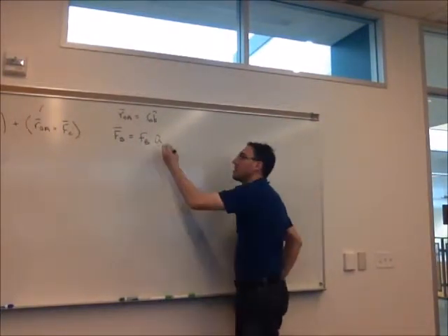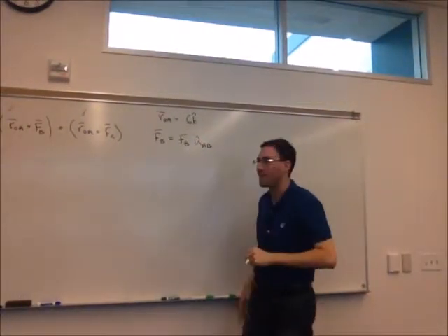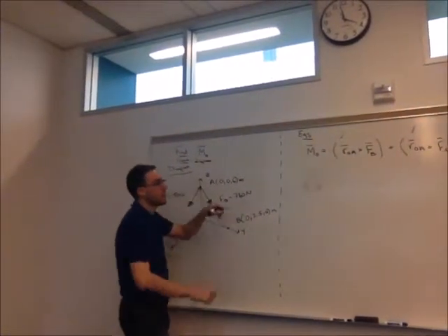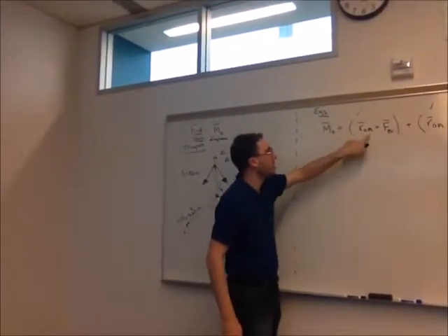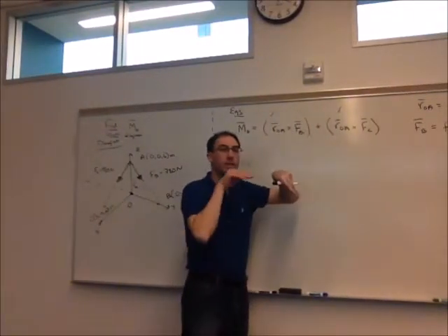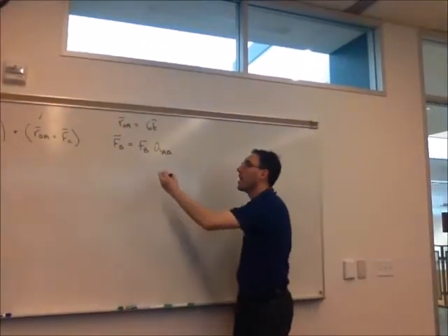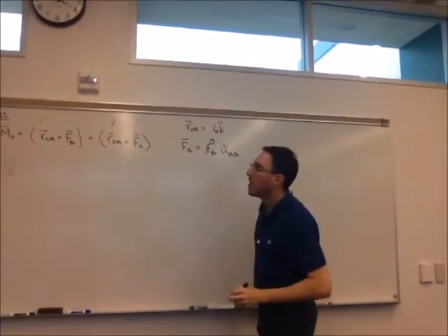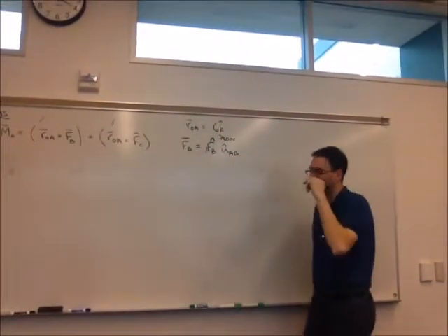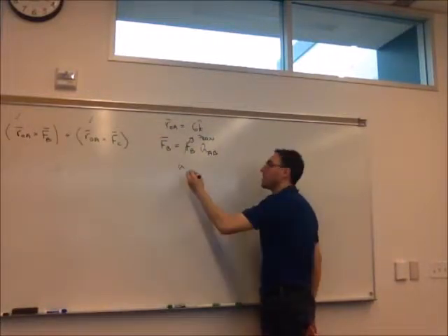Right, AB. So again, this designates the direction of force FB. It points from A towards B. Notice points B and C did not appear. That has nothing to do with this R. B and C have to do with the forces because we need to know their directions. So this is where B and C are going to come into play. FB, we were told off the bat, was 780 newtons. So we need to find U hat AB in order to find vector FB.